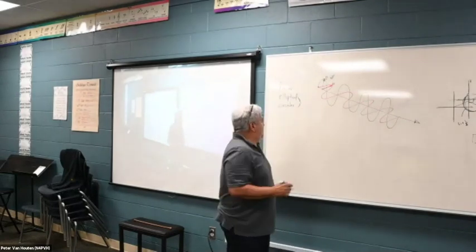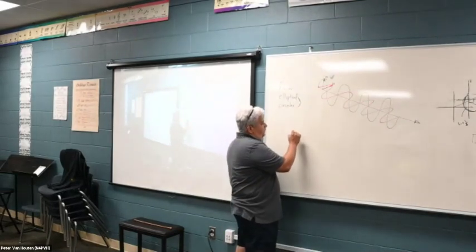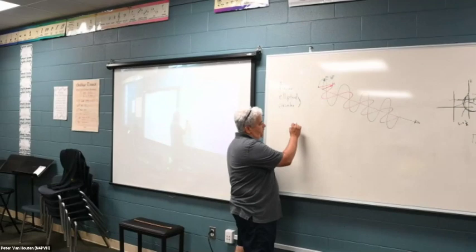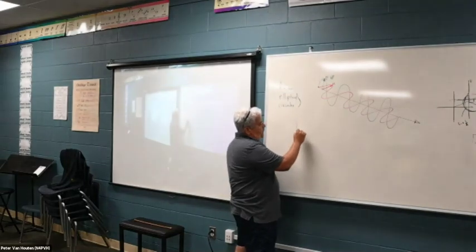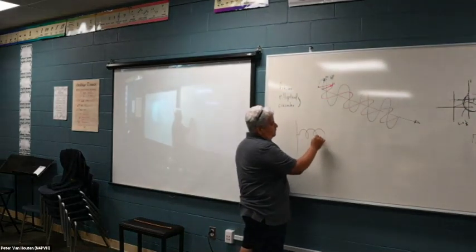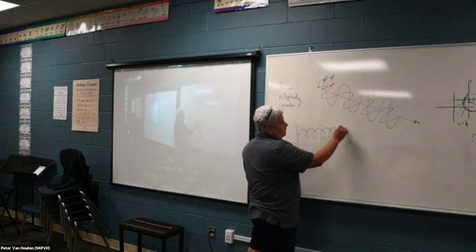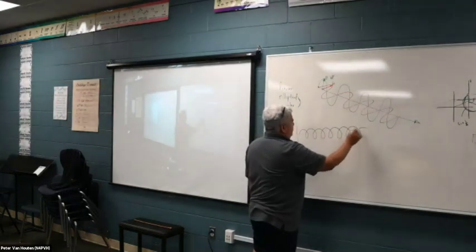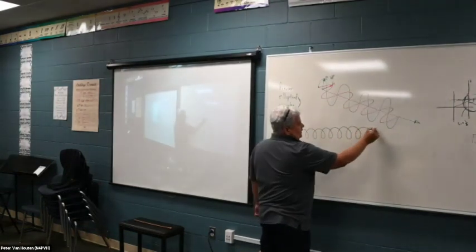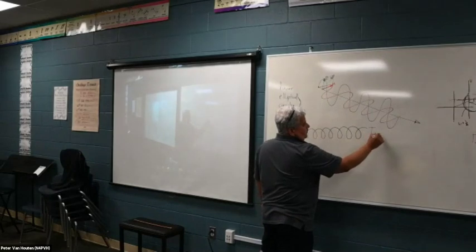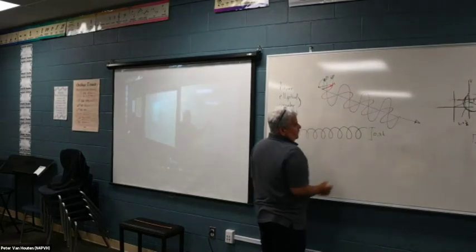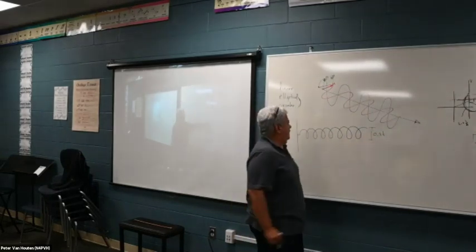Another way to get circular polarization is with one antenna that is called the helix. It's basically a reflector, and then you have something that looks like a spring. General dimensions of this thing are about 0.3 lambda in diameter.